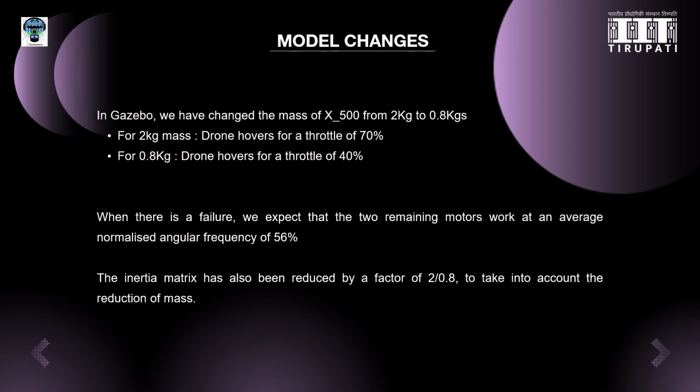Normally a drone is preferred to have a 2:1 thrust to weight ratio, but in our case, since after motor failure there are two rotors which are not spinning, we had to artificially reduce the weight of the drone so that the drone could maintain that 2:1 ratio.